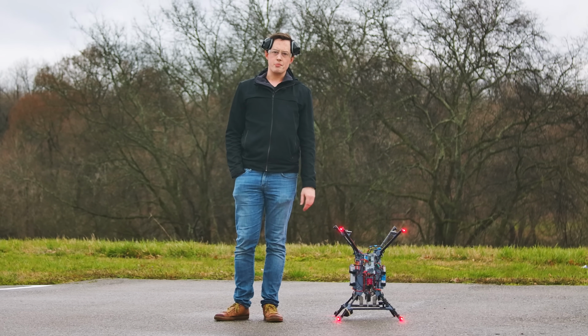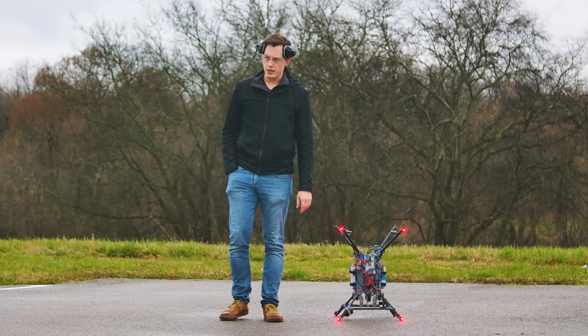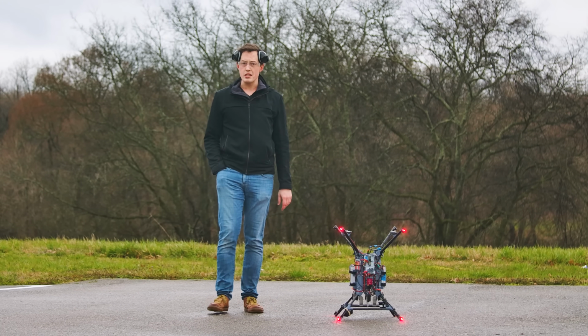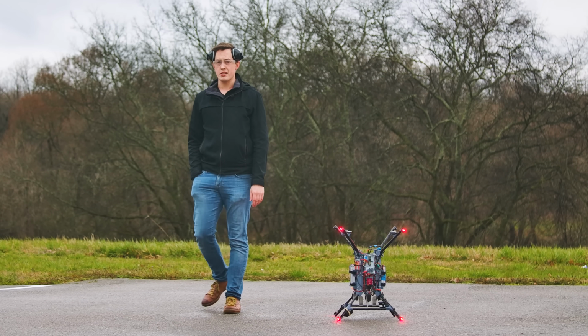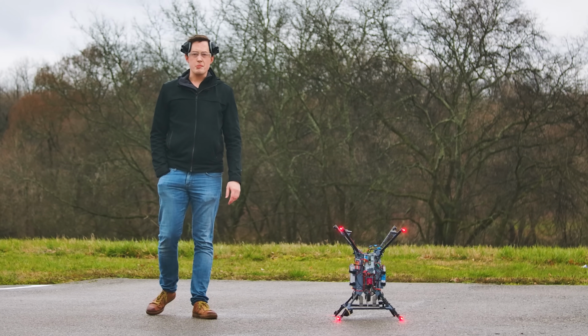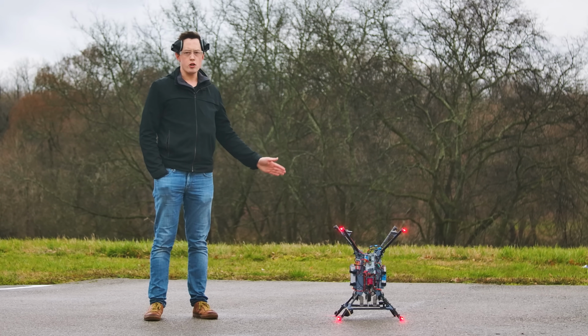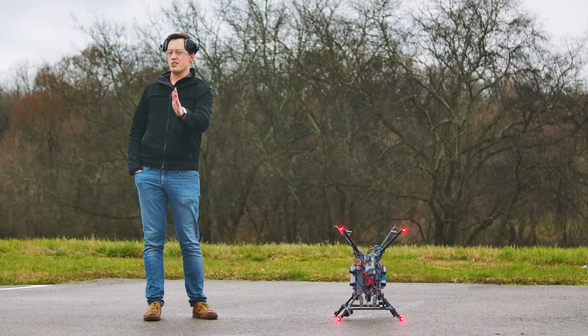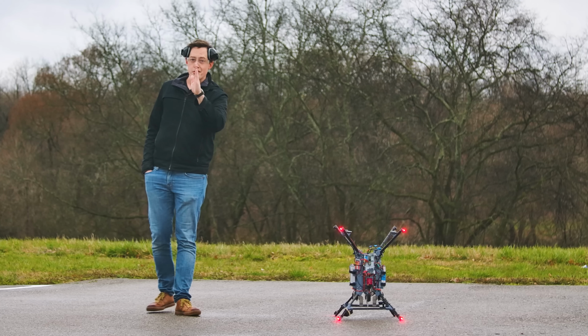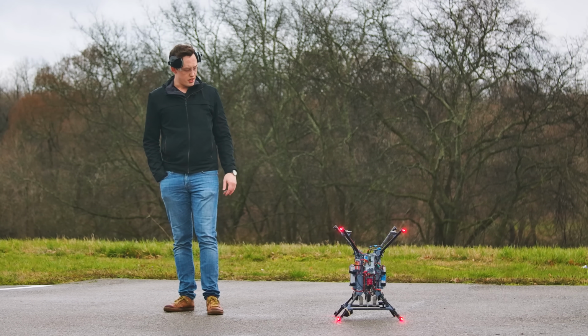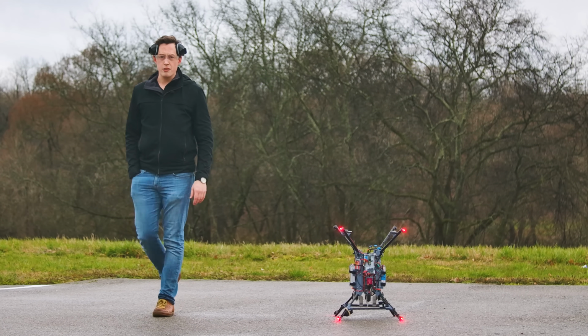I've jacked up the position gains, so we're going to be correcting a little harder against the wind, but because we don't have an integral term in the controller right now, there is going to be steady state error, which is why I expect the craft never to return to the home position, but rather just hold some position, maybe close to the middle. This is a pretty big guess here. I'm going to get the UAV up in the air and we'll get started.